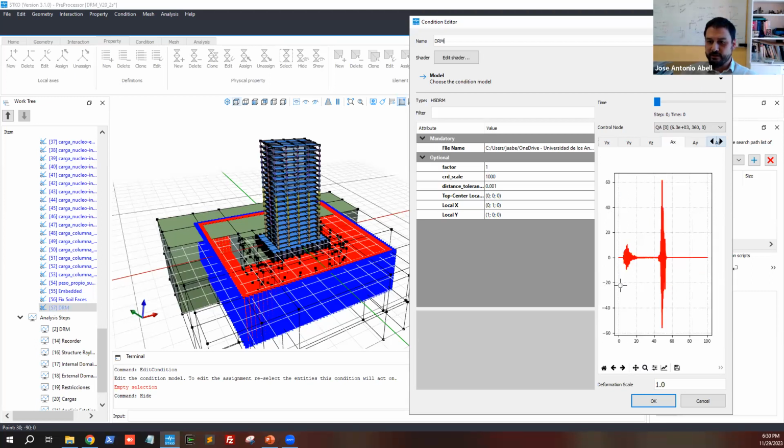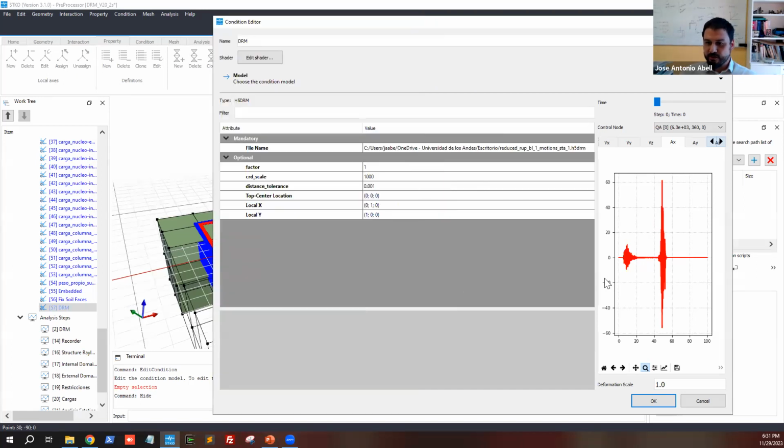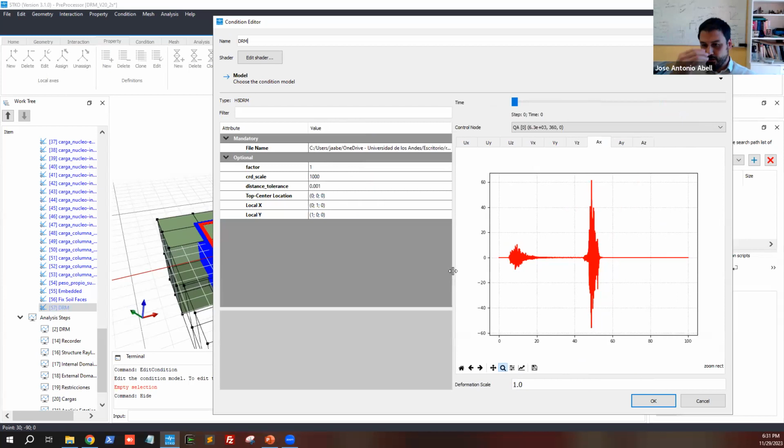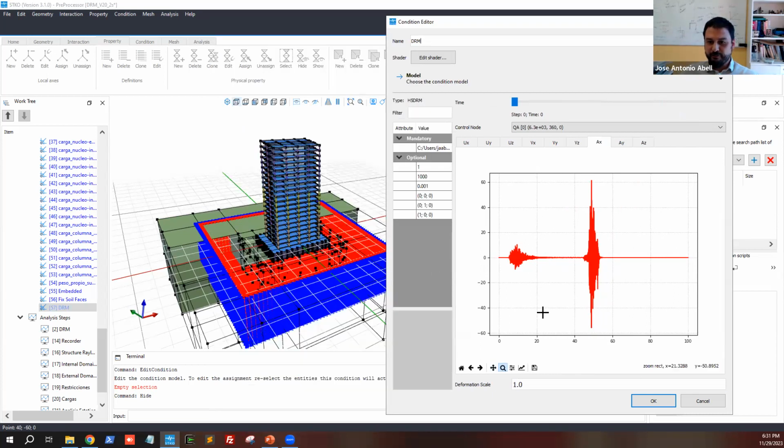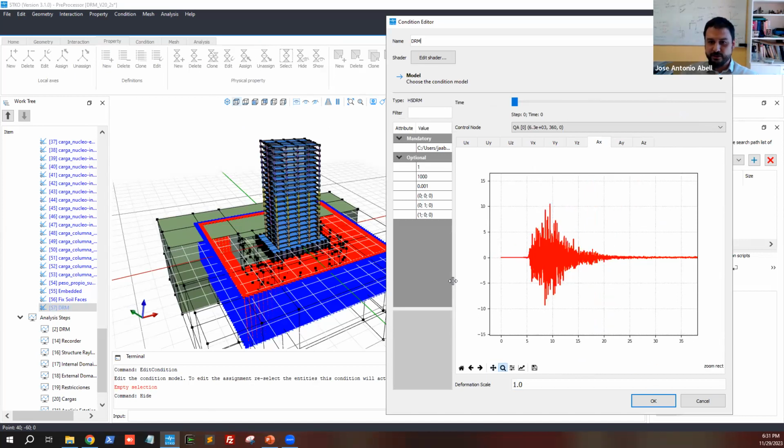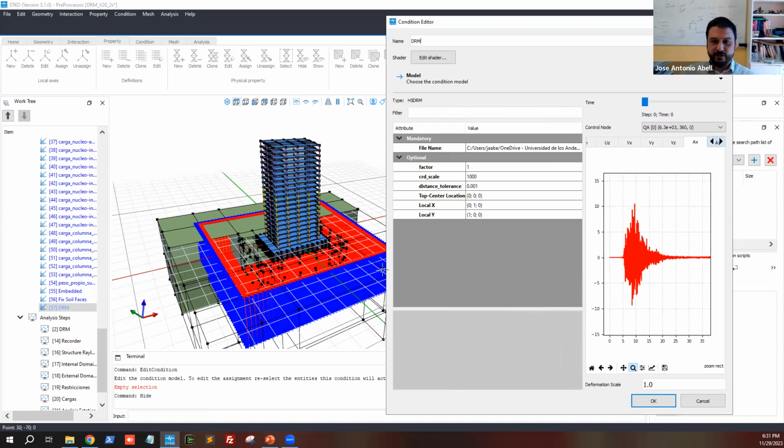So I can look at the accelerations here. Now, forget about this part. The interesting motion occurs in the first 40 seconds. That other part, shown over here, has to do with how ShakerMaker works, because ShakerMaker works in the frequency domain for some computational enhancements. When you're converting back from Fourier space to time, you lose half of the time. So it has to do with the Fourier transformation. But the physical part is this. Those are the accelerations. We're getting about 1g of acceleration in the x direction for this data set.